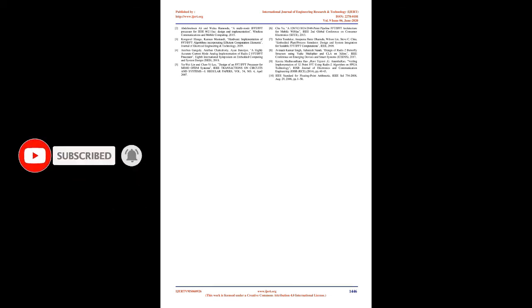Conclusion and future scope. This paper shows that the 16-point IFFT block for complex numbers as well as floating point numbers can be efficiently implemented with very good accuracy by making use of the Radix-2 Butterfly architecture. The results have been extracted. The estimated area was found to be 61% and the delay 42.938 ns. Since the design is scalable and reusable, the future scope of this work is to design for n-point IFFT and compare the computations for complex and floating point numbers, area, and delay associated with it.